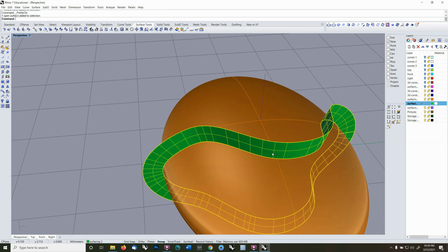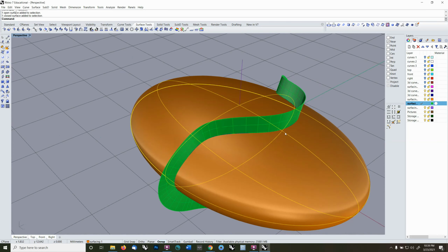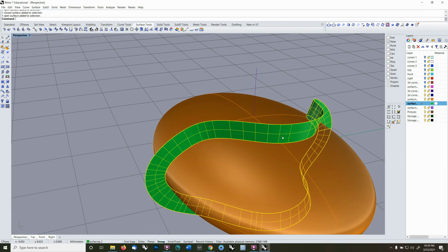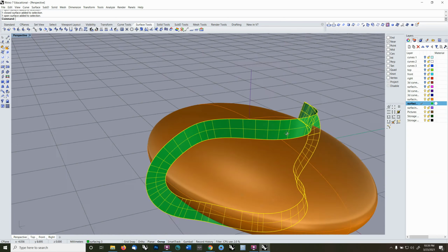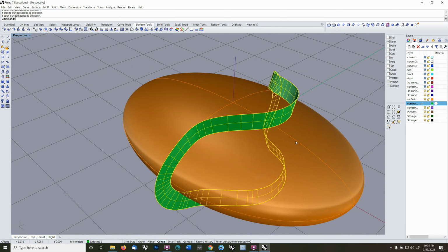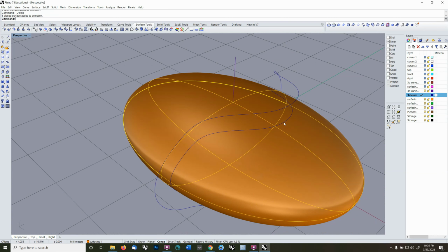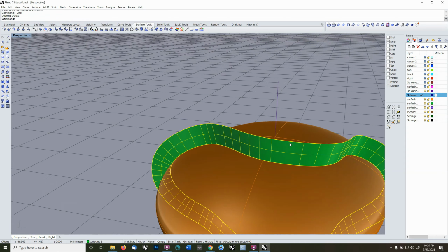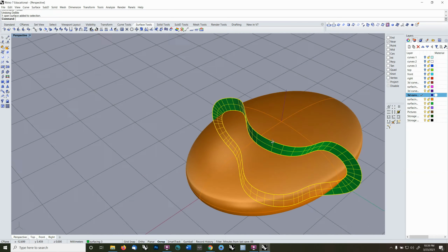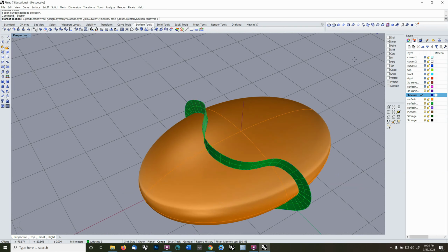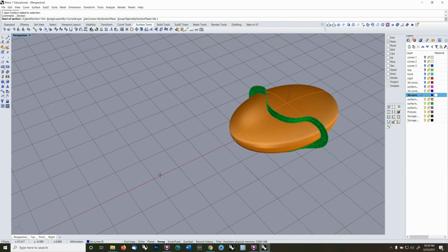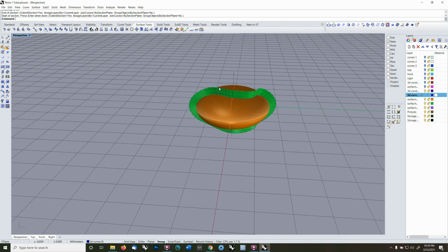Because it's reading not just information from the curve, but the direction, the normal directions from the surface. That means this is not editable, really. It's not a very flexible thing to work with. If you want it to be editable, what you want to do is recreate it by duplicating the edges of it. You might also want a cross-section. And the easiest way to do that would be just to do section command using grid snap straight through. Got a couple of cross sections.